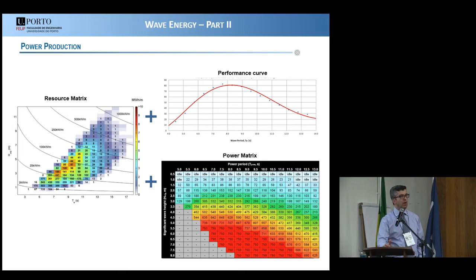If you move away from that frequency, the efficiency goes down. So if you are designing or studying a wave energy converter for a specific location, you should try to adapt the technology at least to have the best performance for the frequency of the sea state with the highest amount of energy. In simple terms, I think that is the approach.